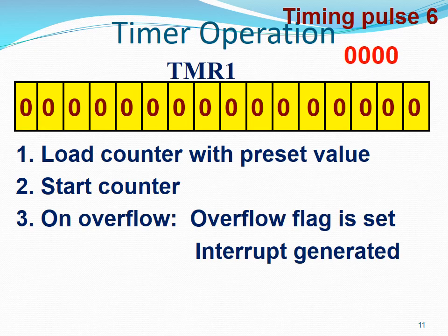When the counter receives a pulse after the timer register has reached its maximum value, an overflow is said to have occurred. An overflow causes the timer register value to go to 0 and an overflow flag to be raised. If configured, an overflow interrupt is generated.